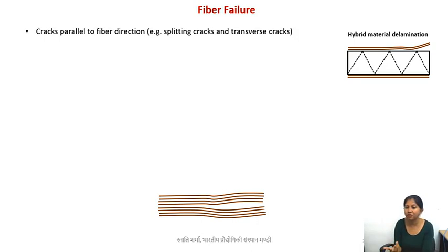Now this entire process, if you look at an individual fiber, the fiber is actually very thin. It can be a few micrometers thin. The diameter of the fiber can be just a few microns. And an individual fiber is actually pretty weak and it can break. However, when we have these bundles of fibers, they are pretty strong. And even if a few fibers break, it does not really compromise the strength of your entire material or entire fiber structure. However, if certain cracks can propagate through the structure, then it is a problem.